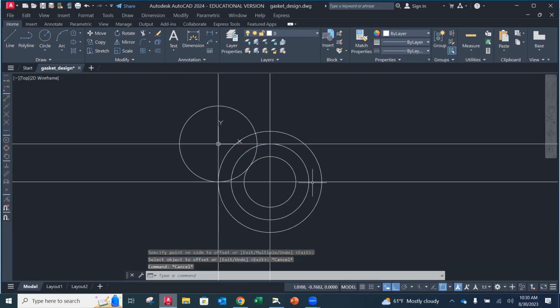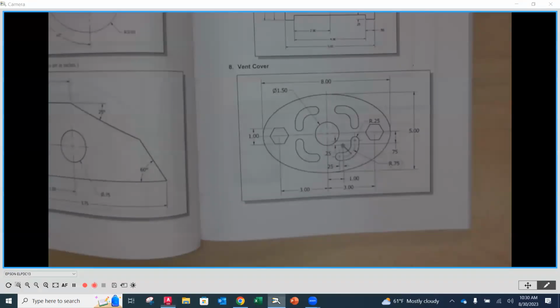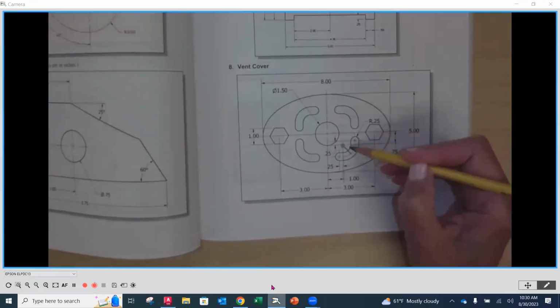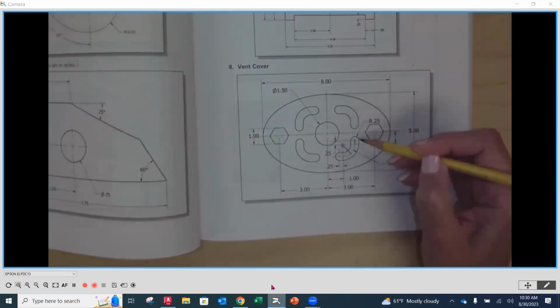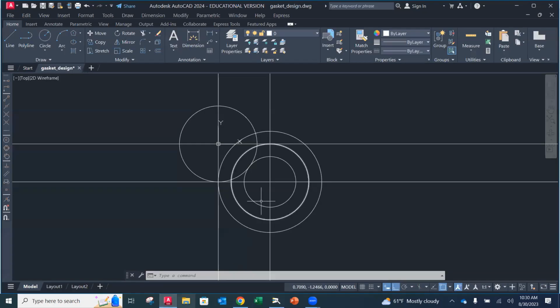I know it looks crazy. It looks really crazy. Okay. Now the next thing we're going to do: when we go back here, I created basically this circle, and this circle. But to get to that center, I have to be up a little ways, and that up a little ways is a 1/4 inch up. More lines. So where I'm at right here, I'm going to offset up 0.25.